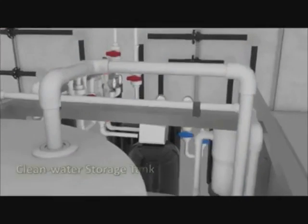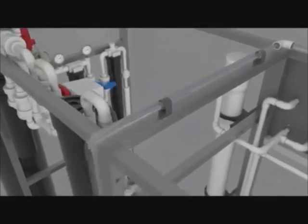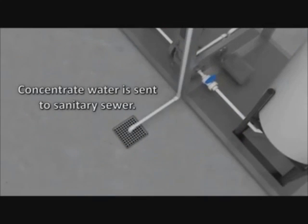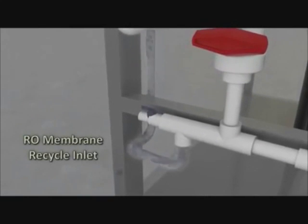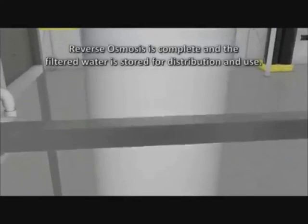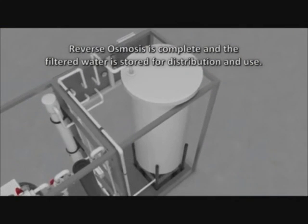At higher salt levels, the concentrate is sent to sanitary sewer, or in some cases, non-critical locations for reuse, also known as gray water recycle. In higher water recovery applications, a small percentage of the concentrate water is sent back to the inlet of the RO membrane for recycle. The salt removal reverse osmosis step is complete, and the filtered water is stored for distribution and use.